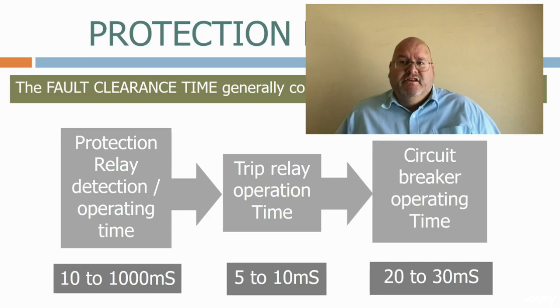When a substation or network is first planned, system studies are done which will define how quickly any fault needs to be cleared to prevent it causing harm to existing plant or a system collapse, where the generators supplying the power drop out of synchronism and disconnect.